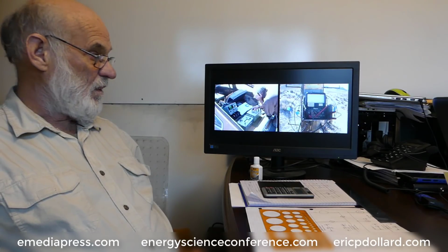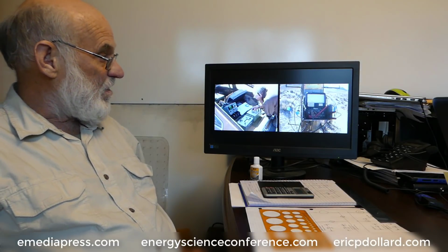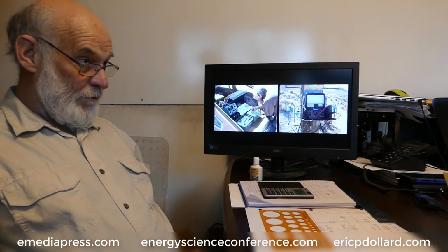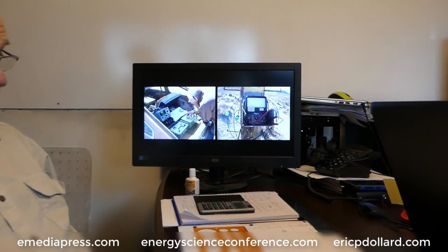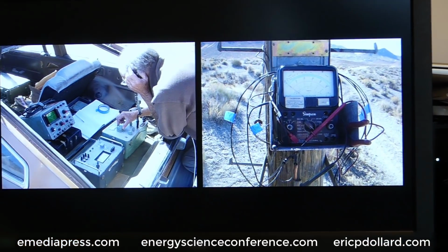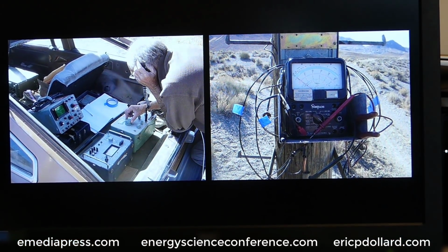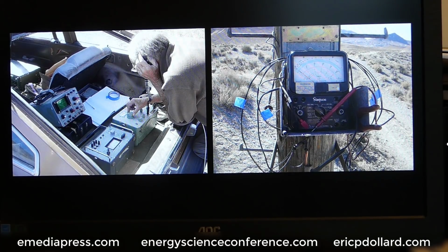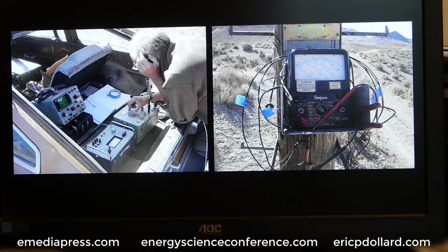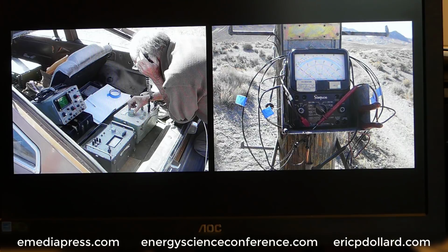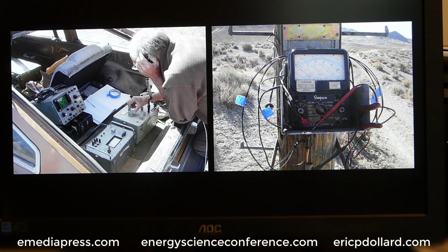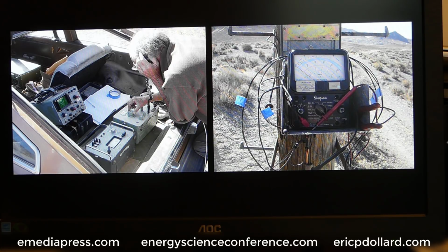What do we see in these pictures here? Okay, this is the test site in Nevada. We have a 2.2 mile long right-of-way, which we can put our wires and cross arms up. So I have the testing equipment in the back of my car, and it's connected to the end of an experimental section of antenna that we put together on the poles. Temporary. It was field telephone wire, so it didn't last, but we were doing our initial investigations here to see how bad the power line interference was.